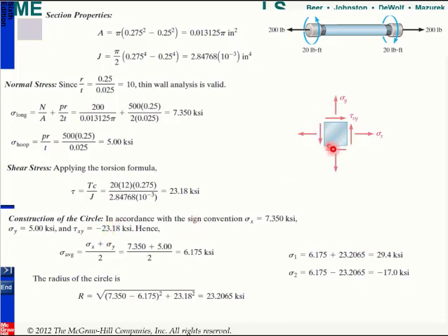So it's also important to determine the correct signs for the stresses. Don't forget that when you have pressure, the longitudinal stress and hoop stress are always tension. And this one can be tension or compression depending on the applied load. In this case it is also tension, so this is why I add them. And my hoop stress is always tension, so I also get this one.